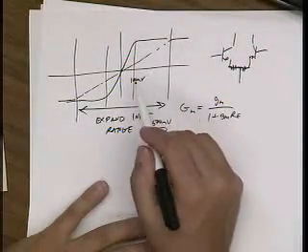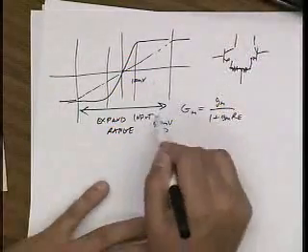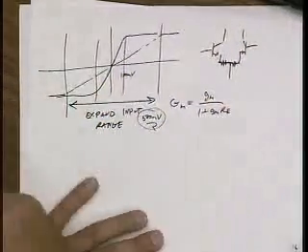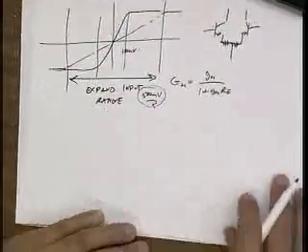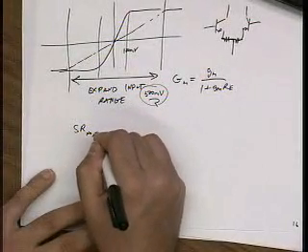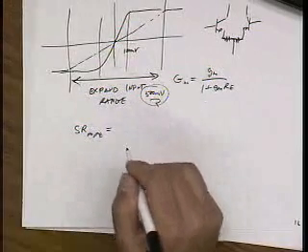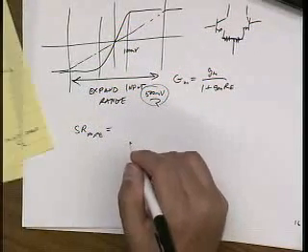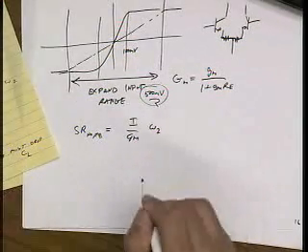That means that before, if a step was bigger than 100 millivolts, it would ramp. Now I can tolerate a step even as large as 500 millivolts, and it still will not ramp. Okay. So let's just compare. So the slew rate with no feedback is 1 over C. It's basically I over GM times omega 2.